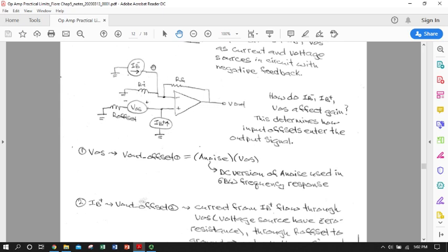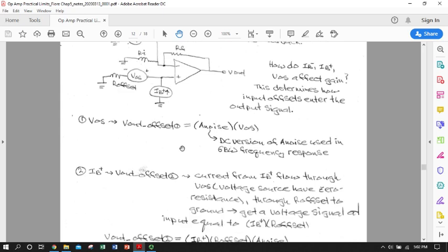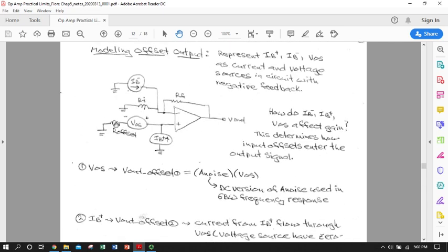So we know that the voltage signal at the output due to this current flow is going to be the result of the voltage drop over RF, due to this point here being a virtual ground. And again, ground having come from here through the short, not from here, because this is effectively an open from a DC standpoint.